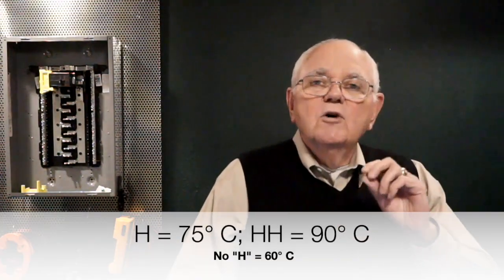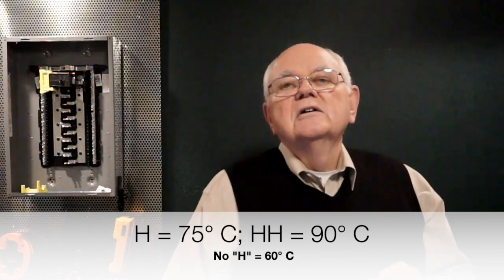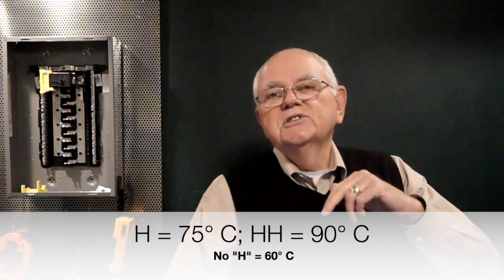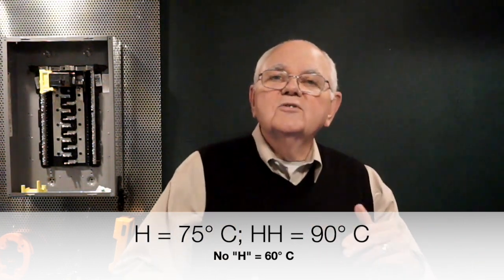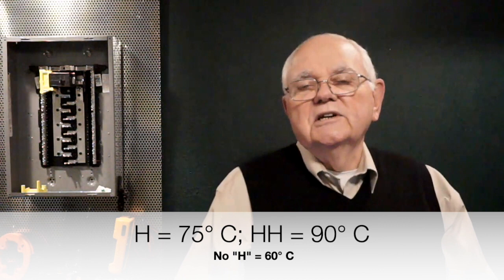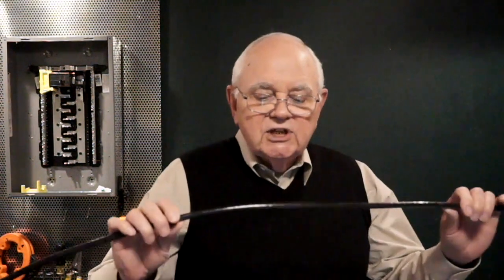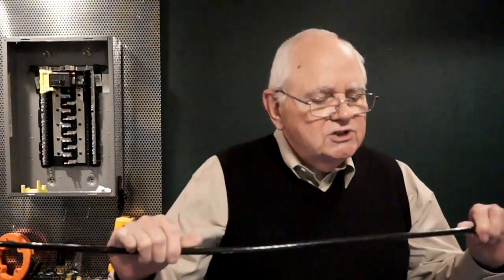thermoplastic. Let's say it's THHN. If it's THHN, 1H means it's rated for 75 degrees C, the insulation is. The other H would mean that it's rated for 90 degrees C, and the N indicates a nylon jacket. If it's THWN, for example, these conductors all say THHN or THWN.